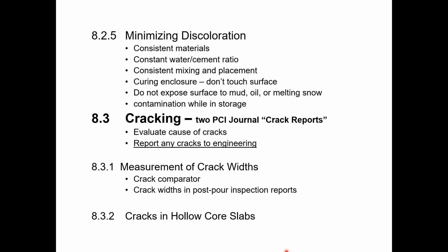And when I say measure the crack, we don't want to just go out there and kind of ballpark it and say, well, it's about a 16th of an inch. You actually want to use a crack comparator to measure those cracks to a very tight tolerance, so that you can have a really good idea of the degree of magnitude of what those cracks represent. So a crack comparator, if you don't know what that is, it's a plastic card about the size of a credit card. It's made out of clear plastic, and I'm holding one in my hand right now, just so I can describe everything to you.